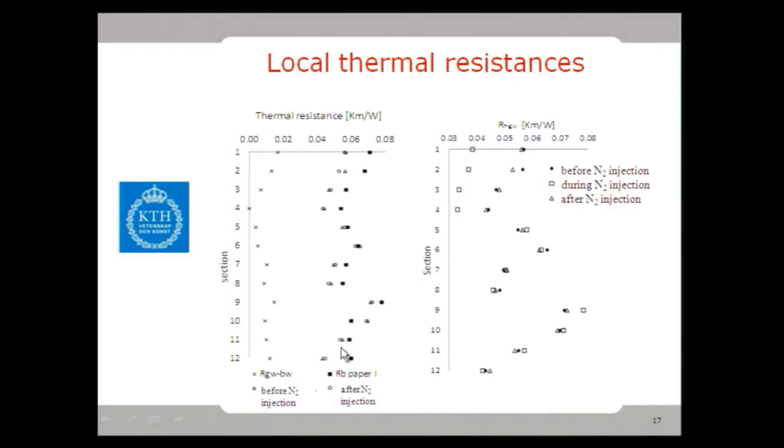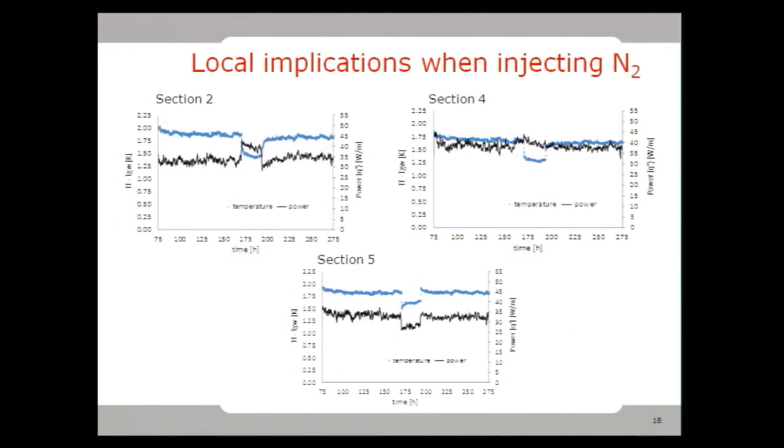These values can all be put in perspective as compared to my results presented in paper 1, where I have the borehole thermal resistances, and then you can see the borehole resistance together with the fluid to groundwater thermal resistance, and even a groundwater to borehole wall thermal resistance, also calculated as in a standard thermal response test. And you see the proportions of these numbers there.